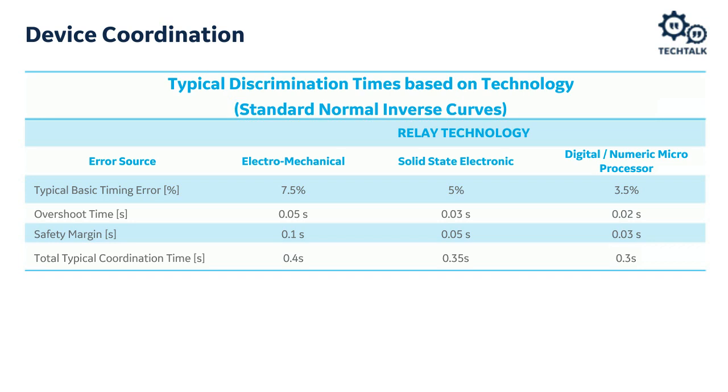And the issue there is that a Fourier transform is a summation type function. So if we immediately stop the current, there will be some small time before the relay starts calculating that it's zero. Or if the current drops below pickup, there is some small time that it will take for the relay to recognize that. So we're accounting for 20 milliseconds for that.